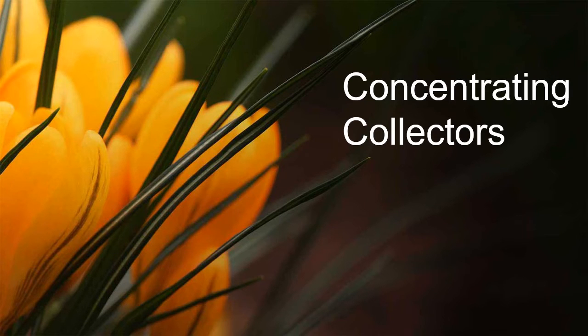Concentrating collectors use an optical system that directs solar energy onto the receiver. Concentration can be obtained by reflection or refraction of solar radiation through mirrors or lenses. These concentrating collectors provide energy at higher temperatures than that of FPCs and ETCs. However, they usually require tracking of the sun. These collectors move throughout the day to maintain a high degree of solar radiation concentration on the receiver.